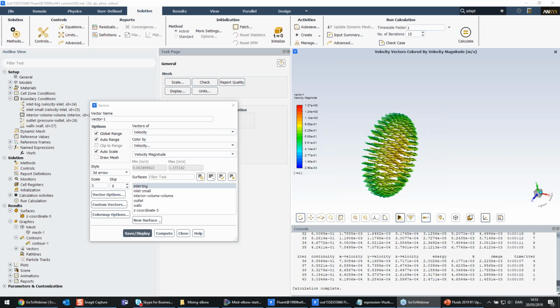No, you always need to do the surface mesh. If you use the Fluent meshing, then you always need to do surface mesh and then volume extraction and volume meshing. But if you have a watertight geometry just like the one that I had, then those tasks would be very quick. It also eases up the task when you want to change your mesh or refine your mesh in certain regions.